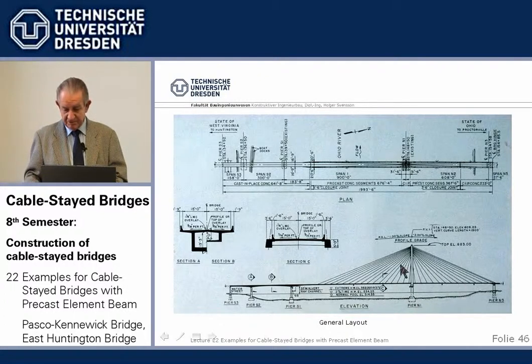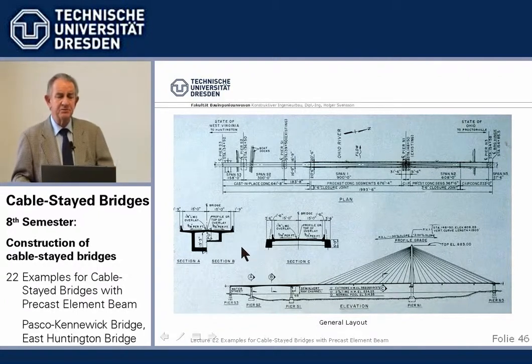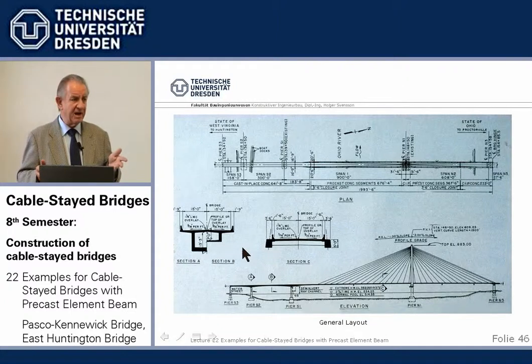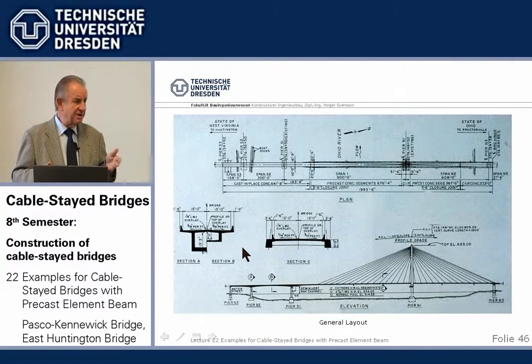And so we had to squeeze on here something which could be taken by the foundations. In concrete, what we did is, first of all, we used, at that time, in the US completely unknown, high-strength concrete, B65. Nothing to it today, but at that time, 1978, unknown.